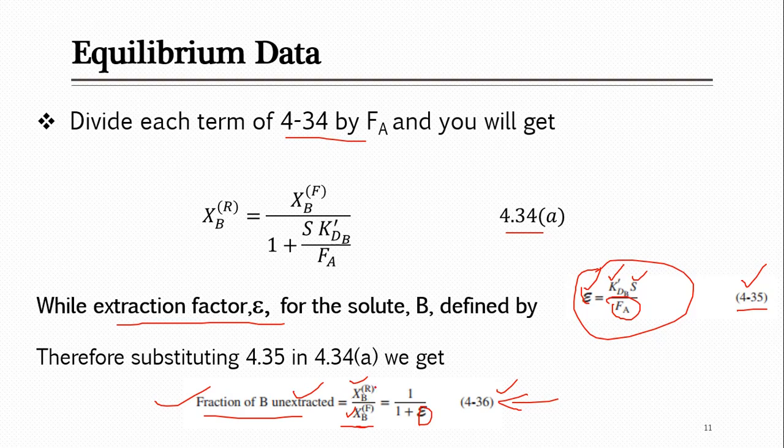And then the other part which we need here, that is XBR. If I need XBR, what does this mean? That is flow rate of acetic acid in retentate stream divided by flow rate of water in retentate stream. Do you know these? Yes, we know flow rate of acetic acid in retentate stream, that is only 1%.